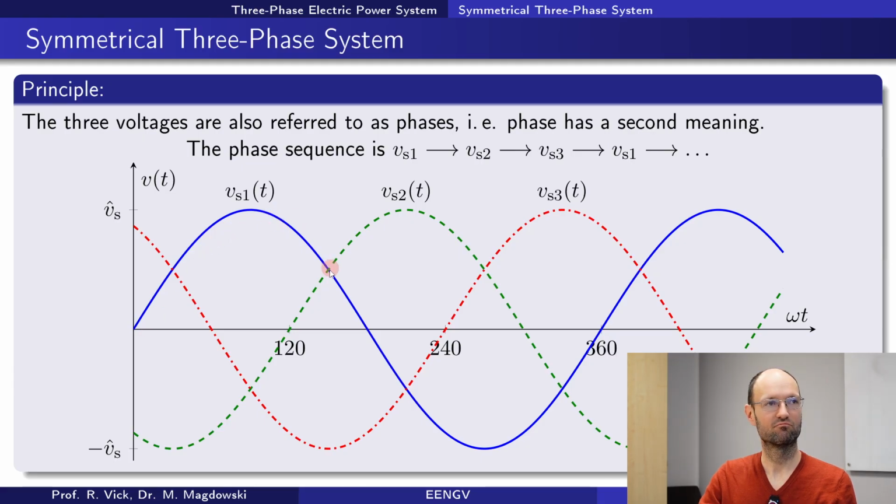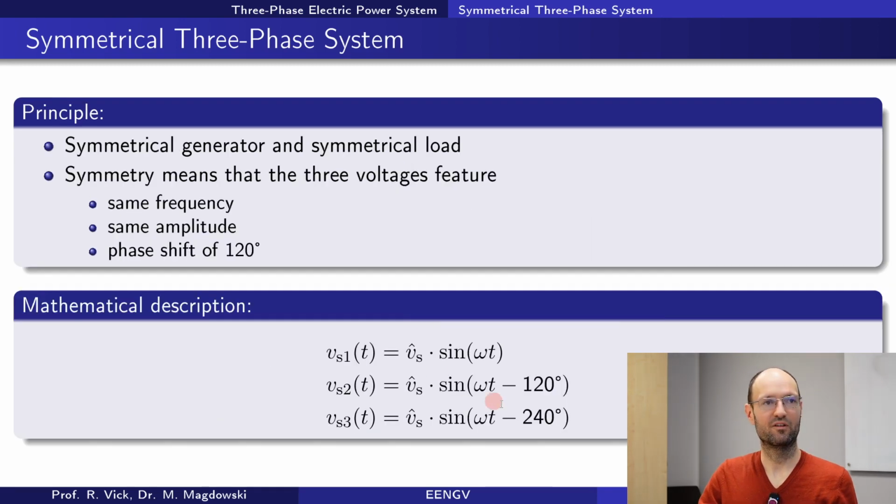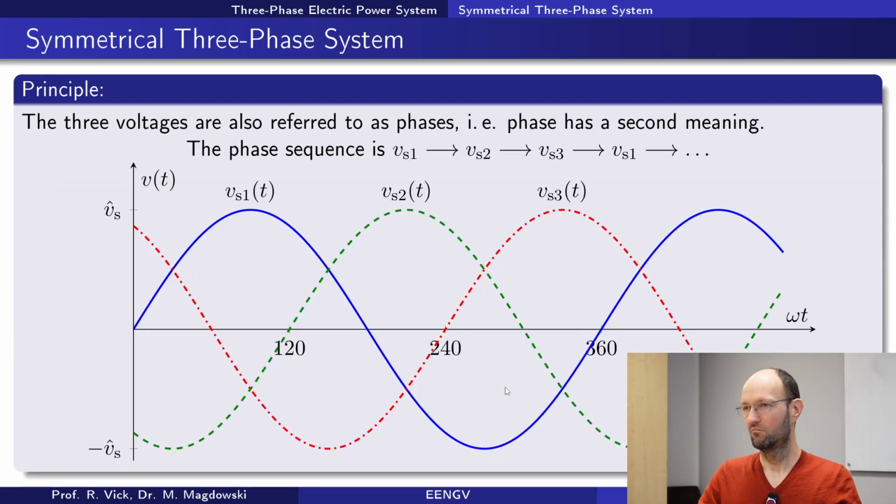If we just plot the first one, we get a sinusoidal curve and 360 degrees. I think here it would be better to add the degree sign for this phase angle, but after 360 degrees it just replicates. If we have a negative phase shift, it means we delay this function. Delay here means, let's say, the peak happens at a later time, or the first positive zero crossing happens at a later time.